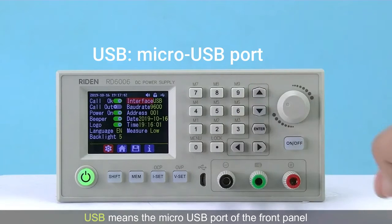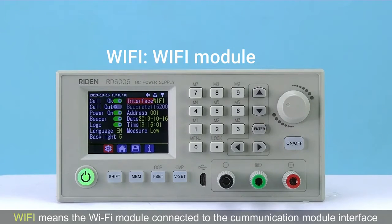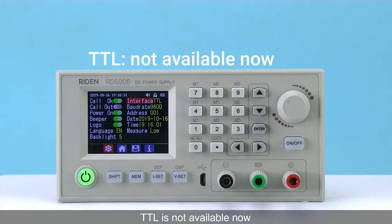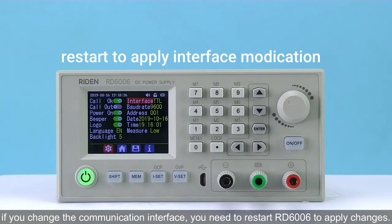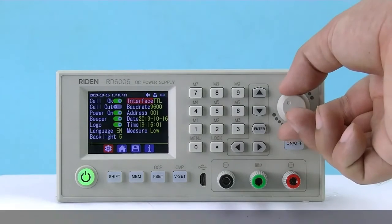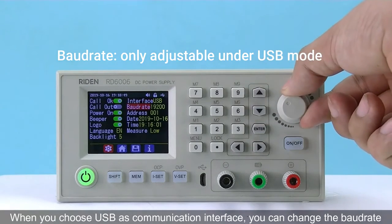USB means the micro USB port of the front panel. Wi-Fi means the Wi-Fi mode connects to the communication module interface. To use Wi-Fi to connect the RD6006 and the mobile phone app, you need to choose the Wi-Fi mode. TTL is not available now. If you change the communication interface, you need to restart the RD6006 to apply changes. When you choose USB as the communication interface, you can change the baud rate.